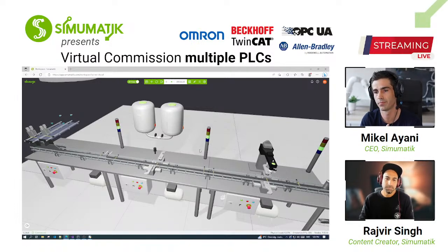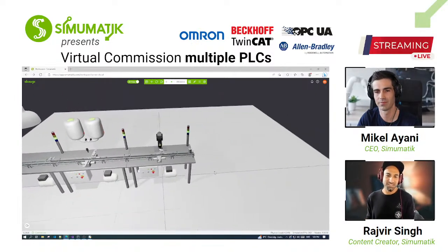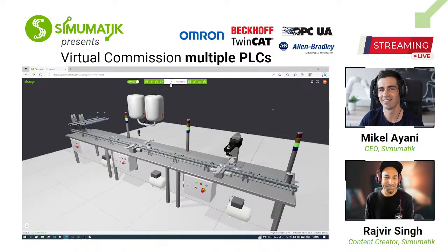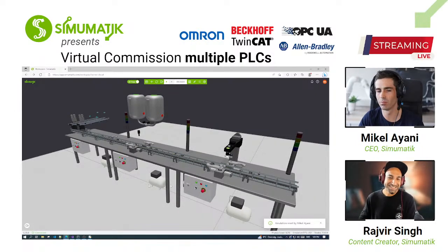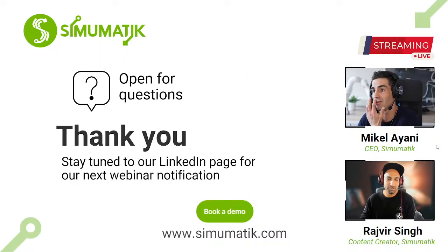Yeah, that's true. And this can also be programmed with just one PLC using the rack module, because you can have multiple IOs and extend. Yeah, of course. I mean, this is the example of having 3 PLCs for this little system. You could just take one, add more. I just want to say, so that audience is not scared that they have to learn 3 PLCs now to do this. They can do it with 1 PLC. Exactly, and this was more just to show that these are the options we have, and all the stuff that we can do here.